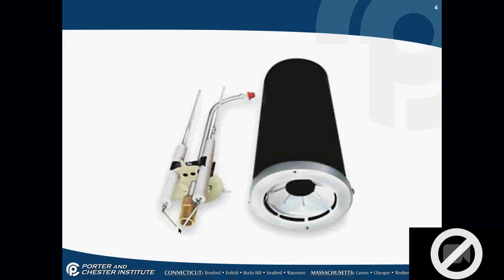So with my oil, I'm continuing to spray oil into the combustion chamber. So I now have oil pooling at the bottom of the combustion chamber. What's going to happen to that oil eventually when it starts to heat up enough if I finally get fire in there? It'll evaporate and boom. But it might not. It's going to eventually have an uncontrolled combustion in there. So it's very important that these igniters be lined up properly.